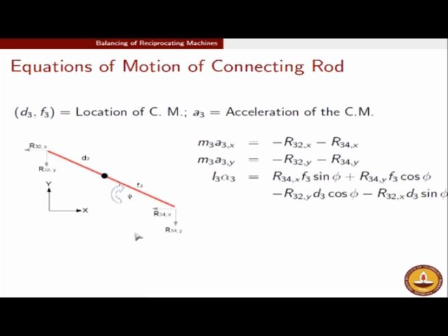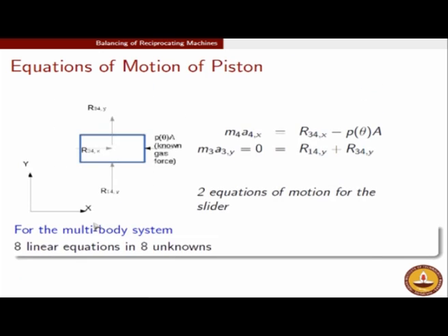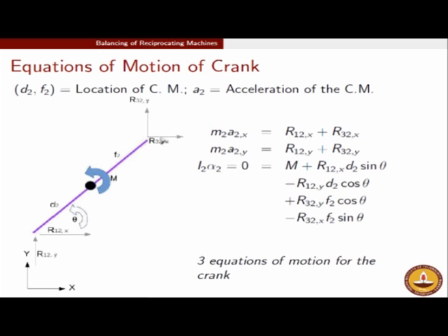So you are right in saying that the reaction forces are varying in time. The reaction forces here are varying in time, but let us say this moment could also vary in time such that the total moment is 0, and that is exactly what we are trying to enforce through this condition. So if you look at this equation, all the moments taken together is 0. So we are trying to ensure through the application of this moment m, which we are calling load torque, that this total summation should give us 0.